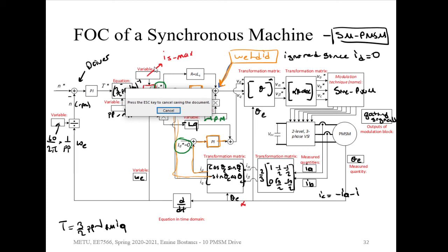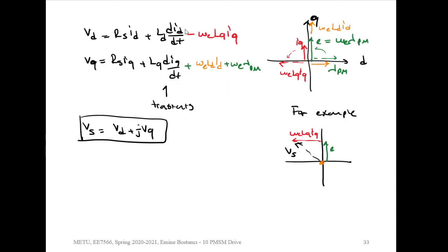Okay, so basically in the control loops, we are trying to have a PI controller to control the ID and IQ, plus we apply feed-forward loops that include the terms in this equation, so that the system will depend less on the current and less on the speed, because these quantities all depend on the speed. If we add them as feed-forward loops, then we will make sure that our controller is the same throughout the operating conditions.